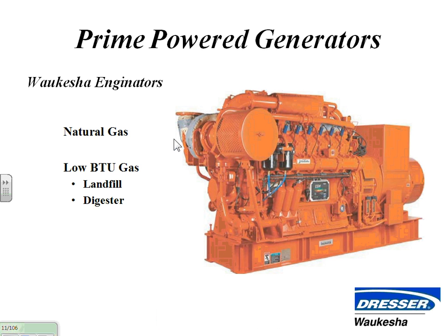Also within our product line is the Waukesha generator. This is not a standby product at all. I just wanted to show it one slide to you and let you know that this type of product exists. What it's for is primarily cogeneration markets. These are generators that are going to run all the time. So what you're going to see is sleeve liners and things like that. A lot heavier duty engine. Very rebuildable. You can build these things over and over and over again. So they tend to be a lot more expensive than a standby product, but they're designed to run all the time. Take heat off the engines to use in processes.